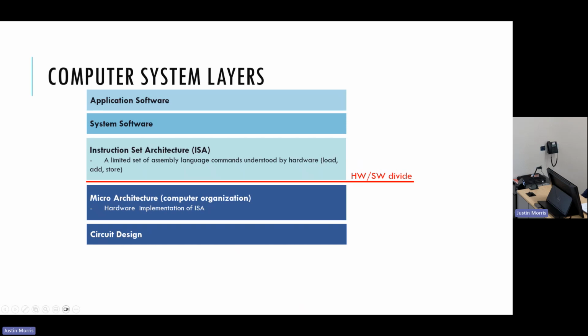And then below the microarchitecture, which consists mostly of these blocks of standard components that are connected. So one thing that you will see in the future, we won't talk about it too much in class, are multiplexers. Multiplexers are just blocks that are selecting between multiple inputs to an output.